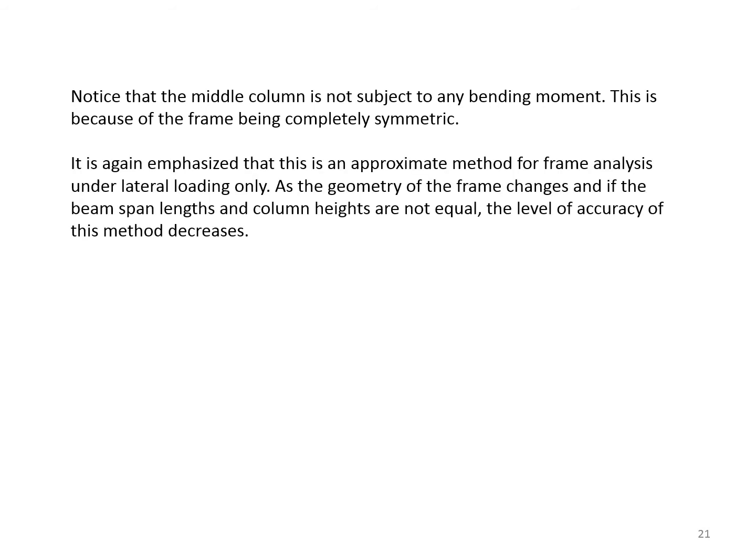It is again emphasized that this is an approximate method for frame analysis, under lateral loading only. As the geometry of the frame changes, and if the beam span length and column heights are not equal, the level of accuracy of this method decreases.